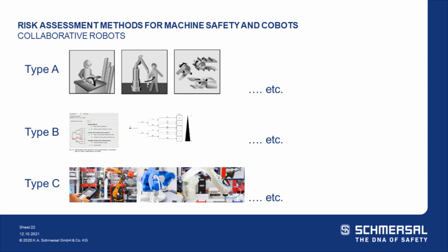Type C will always supersede, but you'll see that in these Type C standards, when it comes to controls, for example, it'll say, please refer to ISO 13849, and that's a Type B standard for performance levels I discussed. Or if it says, hey, review some of the guarding, it may refer to ISO 12100, which is a Type A. But yes, you're 100% correct in your understanding that a Type C will supersede a Type B and A, and a Type B will supersede an A.